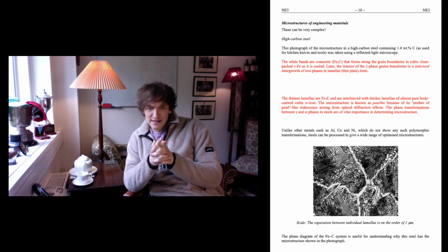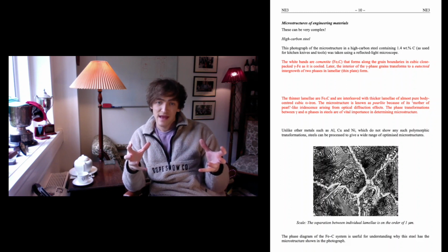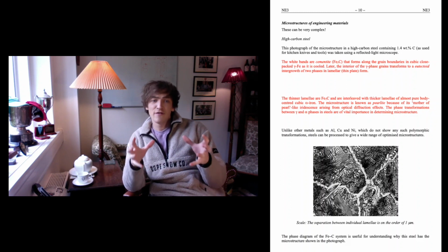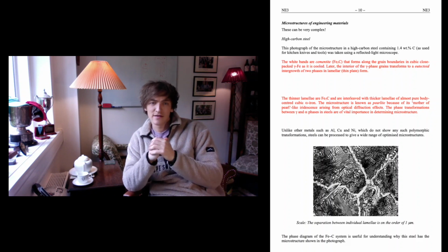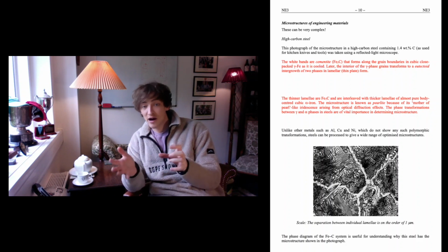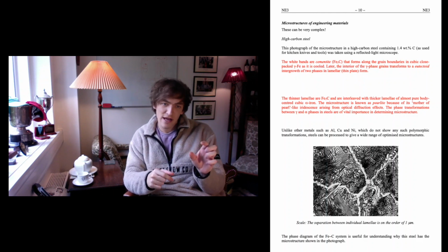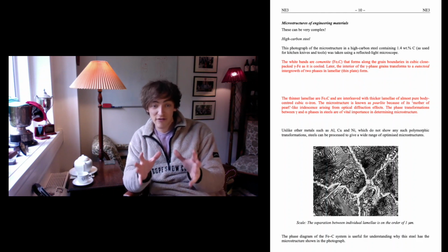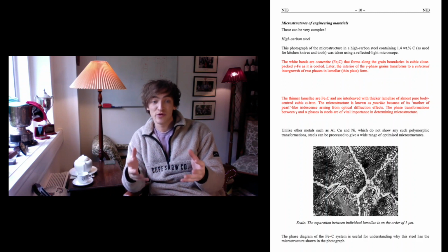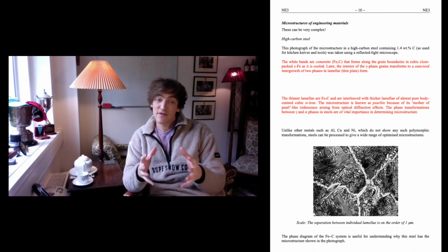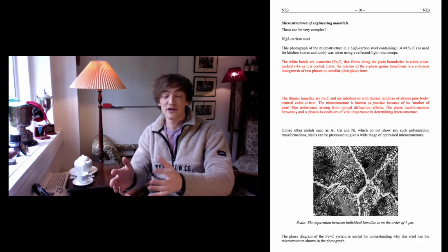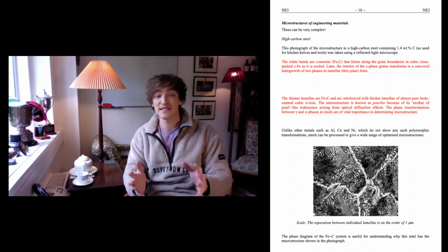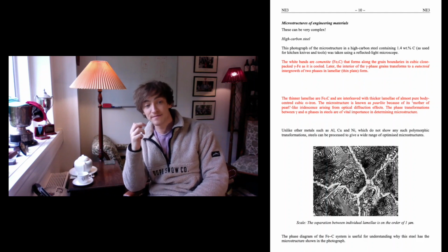Now the zebra-like interior of the grains that you can see in the micrograph, that's called a eutectoid. It's a eutectoid intergrowth of two different phases, forming these very fine lamellae of cementite, the iron carbide, and alpha iron, aka ferrite. So that's more pure iron. Another phase, that's just another phase of pure iron, and it's body-centered cubic. I've mentioned austenite, that's face-centered cubic. That is another phase of iron.